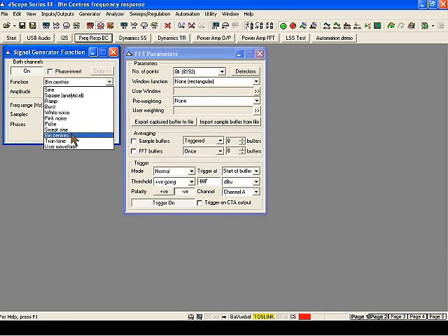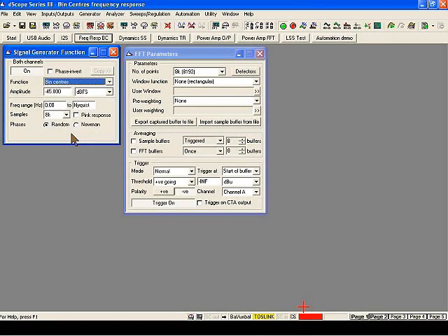What is that? Well, it's a very densely packed multitone that has, in this case, because of the selection that I've made here, 8,000 tone components within it. Actually, technically, there are just over 4,000 tone components in the real frequency axis between DC and the Nyquist limit, or whatever frequency range we specify.